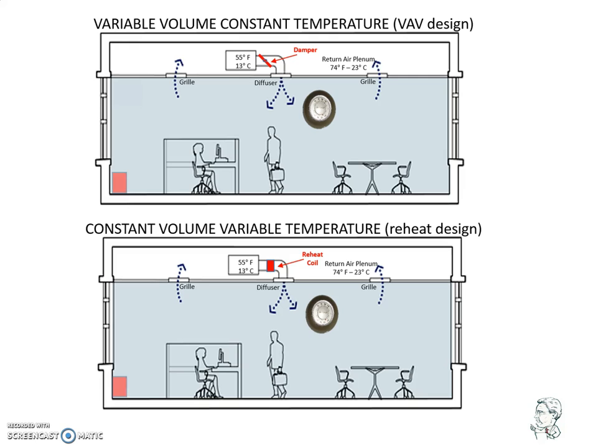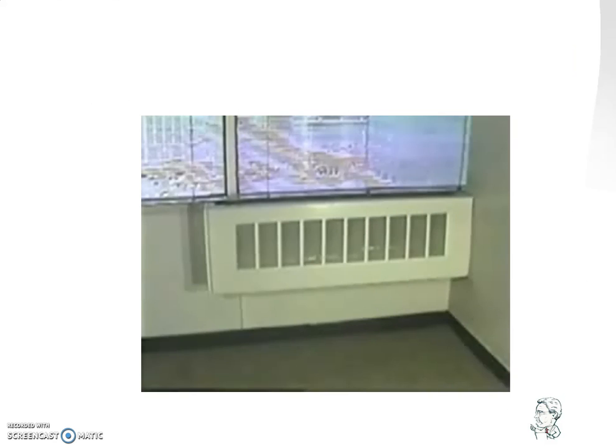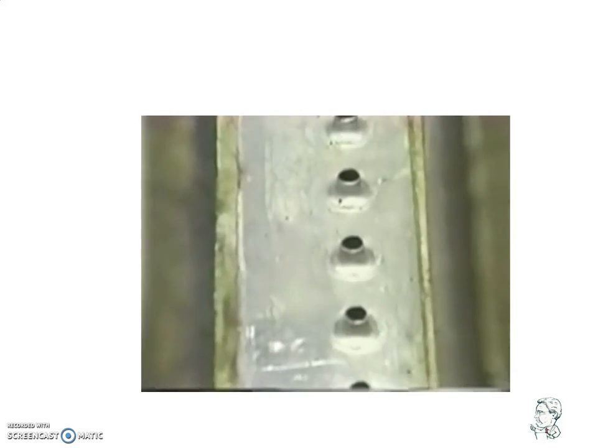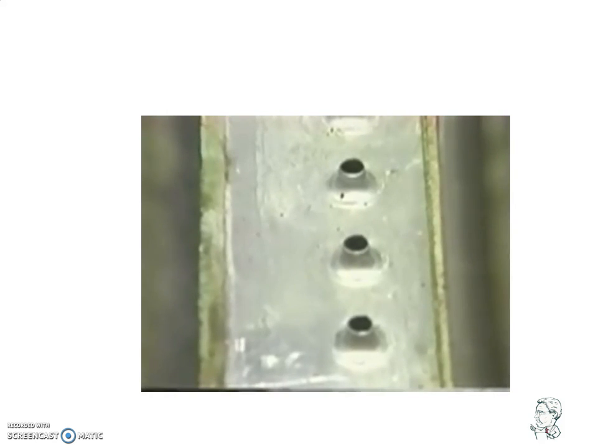This heating installation can either be a simple radiator design or an induction unit design. An induction unit is an air supply unit located along the outside wall. This unit has a supply air duct feeding several nozzles, constantly discharging air vertically upward.